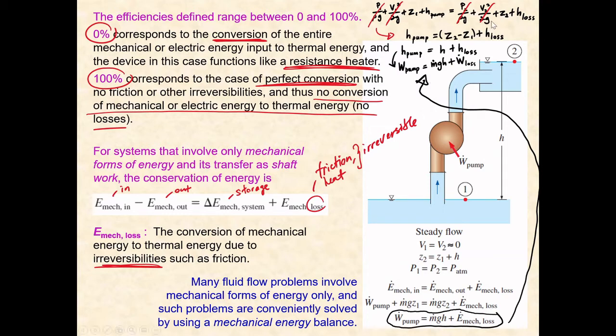Alright, when you look into this equation, if you try to solve it, you can see that point 1 and point 2 are open to the reservoir. As a result, the pressures P1 and P2 can be cancelled out because both are at atmospheric pressure. V1 and V2 are both at the reservoir surface. If you look at the surface at point 1 and the surface at point 2, they are relatively constant, not moving that much.